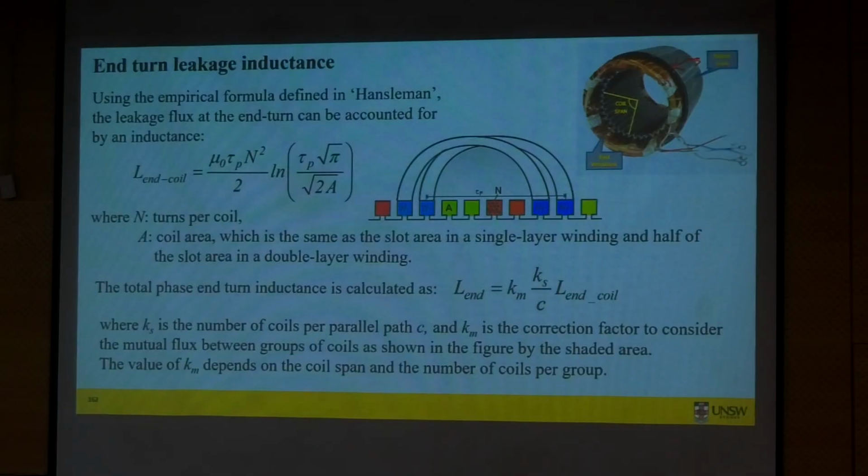The flux related to this end part is accounted for by an inductance known as end turn leakage inductance. Two-dimensional finite element cannot account for this.